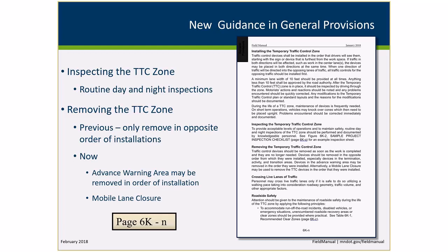So if you're working on a freeway where your interchange spacing is 5 miles apart, the technically right way from the previous field manual is that you could remove those channelizing devices. Then, if you don't want to back up on the shoulder, which there might be good reasons for, because you might have to back up 1,000 feet between each of the advanced warning signs, you would drive ahead to the next interchange, do a U-turn, come back around, and then remove that third sign. Then you'd have to go find that same interchange, go back around and remove that second sign, and so forth. So that's a lot of driving around to remove signs.